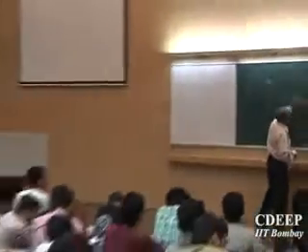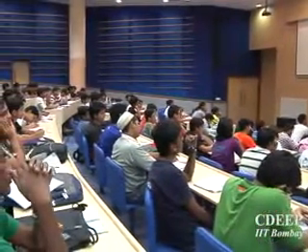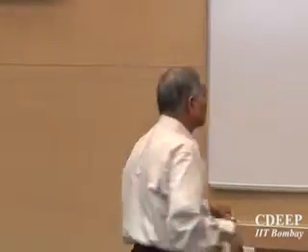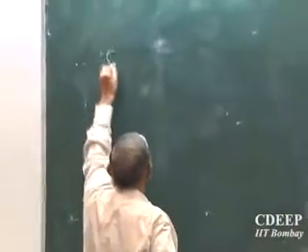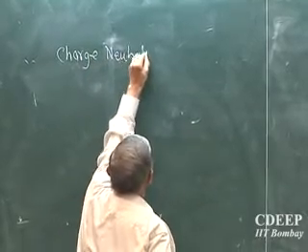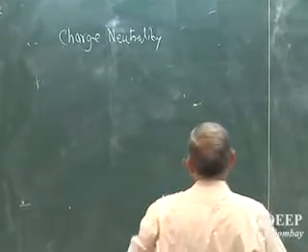Now, another worry for me: let's say you have both NA and ND in the same material. Electrons carry negative charge, and donor ions carry positive charge. So are we trying to say that the silicon is N-type, and if I touch it, I will be shocked? In reality, it does not happen. Charge always remains neutral. So charge neutrality always rules.